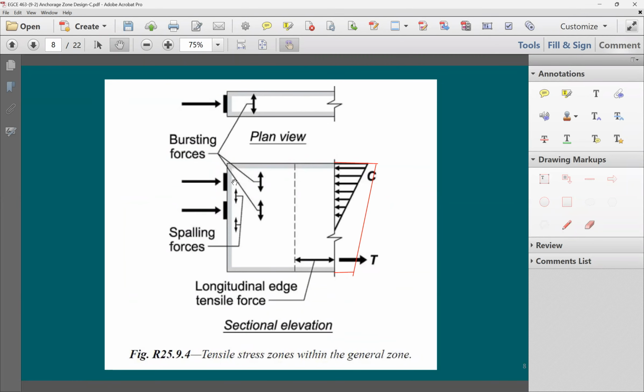Therefore, you're going to have here more stresses than this side. If you have lots of eccentricity, you may end up with a situation like this. But if you have less eccentricity, at a certain point, once you bring this point load to the mid height, your stress distribution is going to be completely uniform. So it depends on the amount of eccentricity, and you may end up with some maybe tension at the bottom and compression on the top.